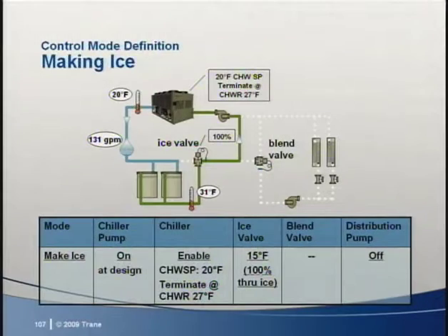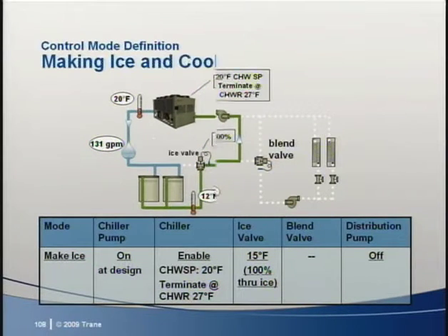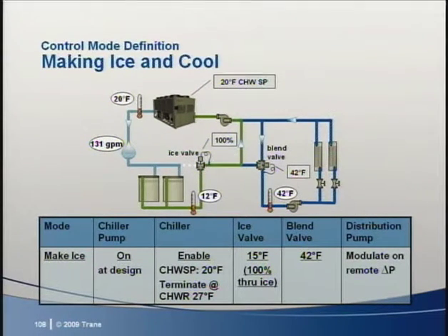This logic is so reliable and standardized it is built into many chiller control systems from the factory. The ice storage selection tools such as Ice Pick tell us the appropriate termination temperature based on the ice tank selection and the system design. While diagramming the system operation, it is extremely useful to document each component's operating conditions in a tabular form. This can be invaluable not only to the BAS technician, but when commissioning the system as well. Here is the mode that is sometimes overlooked: make ice and cool simultaneously.